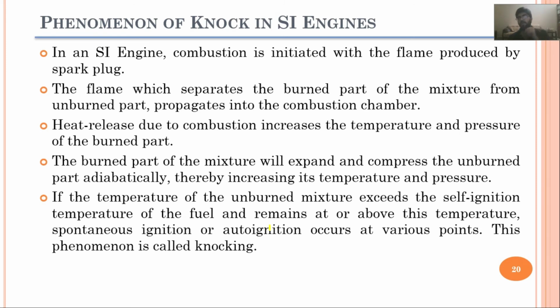I have already explained this in the previous topic. Knocking is undesirable, and it usually happens when the fuel air mixture inside the combustion chamber self ignites, which produces an undesirable audible sound, and it is called knocking. It can also have drastic effects on your IC engine.